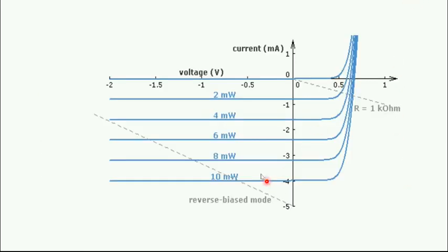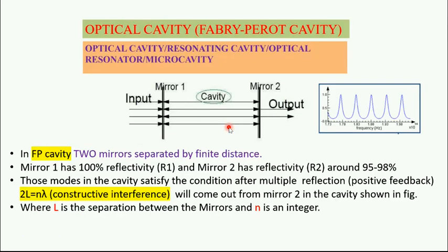Okay. So the photocurrent generated is proportional to the absorbed light intensity. This is a characteristic of a photodiode, and you can see that when light intensity increases, photocurrent also increases. For 2 milliwatt light power, approximately 1 milliampere current, and for 10 milliwatt light intensity, you can see 4 milliampere. So the photocurrent increases with the light intensity falling on the depletion region, right?